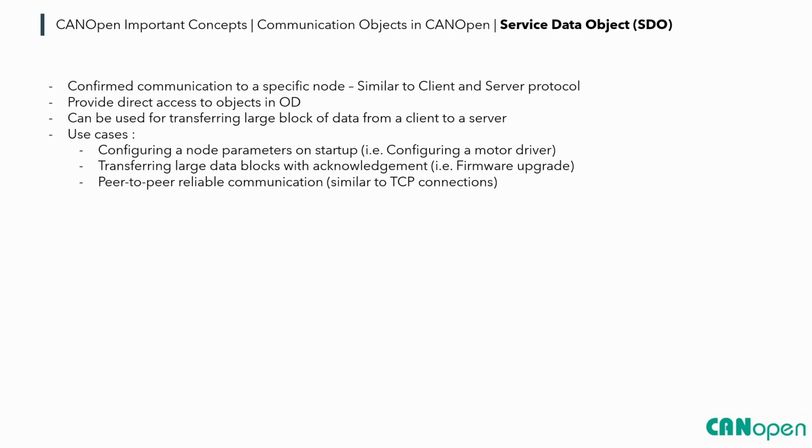Okay, so basically a master or a manager in the network will initiate an SDO communication and ask node 1, which here is the server, to update its node ID to, let's say, 3 or 4. So here we have this SDO, and we talk directly P2P to the node that we want to update its ID.